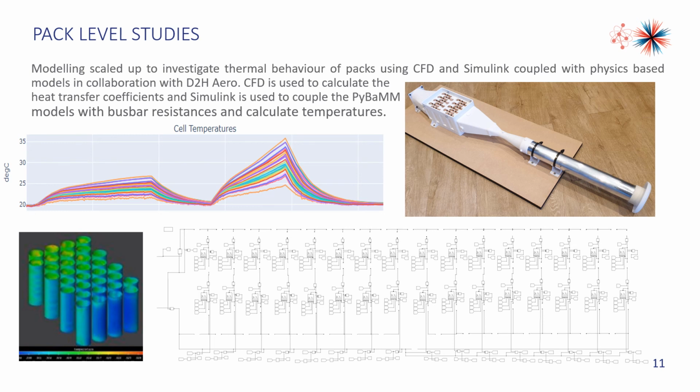And so the rig is fully sensored. It has 32 21700s in a 16P2S configuration, and the cell temperatures that we're measuring in the rig align very well with the model predictions as well. So there's good promise here to take that forward.